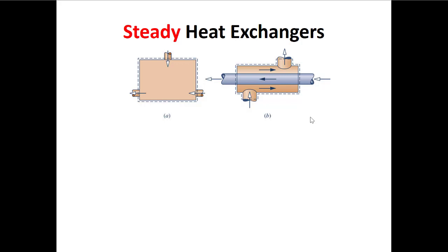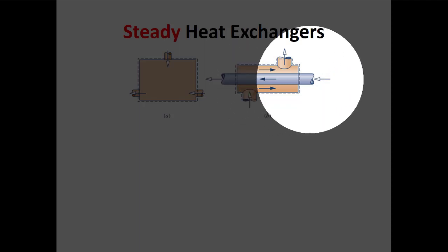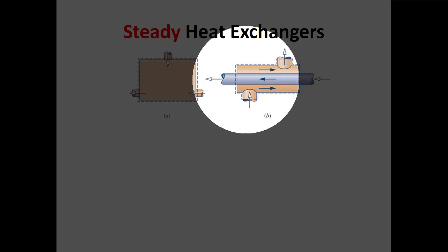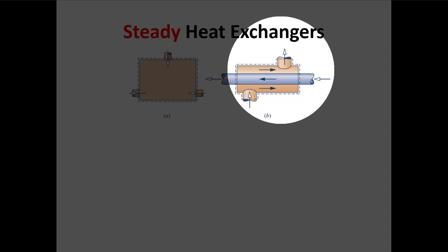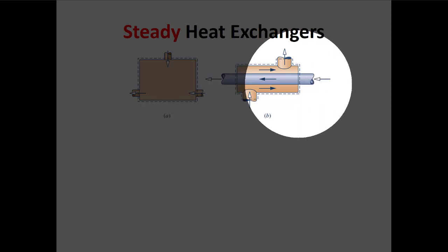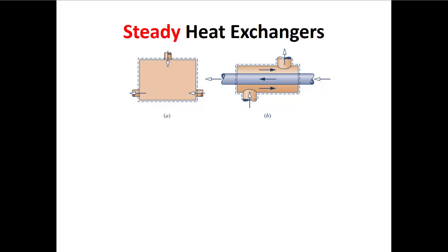Okay, so heat exchangers can be a little bit trickier, right? There are two different kinds of heat exchangers we can think about. One is a shell and tube heat exchanger. Here you have two fluids that don't mix. One fluid runs through the tube, and it doesn't mix with the fluid that runs over the shell. So maybe you have water on the outside and hot oil on the inside, and this is used to cool the oil down, right? You don't want to mix the water and the oil together inside of a basin to mix the heat, right?